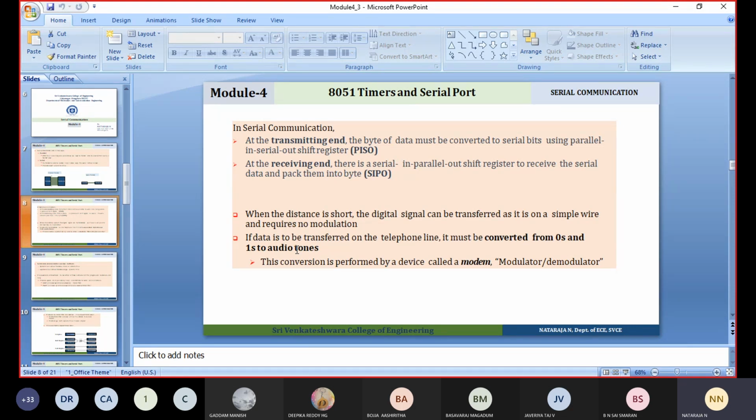There is a block diagram to convert an analog to a digital signal. First, I'm going to make samples. I'm going to apply the sampling theorem to the given signal and divide it into samples by making use of the sampling theorem. Next, I'm going to use quantization. I'm going to set the levels of quantization, either 0 volts, or 1 volt, or 2 volts. I'm going to map the amplitude of that voltage. I'm going to use a quantizer.